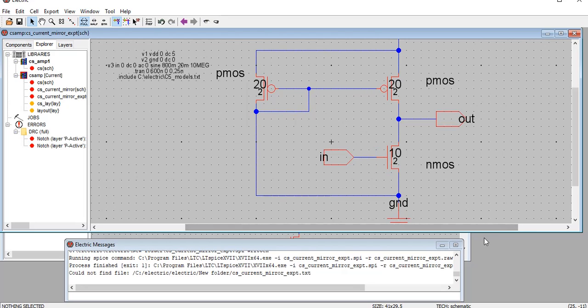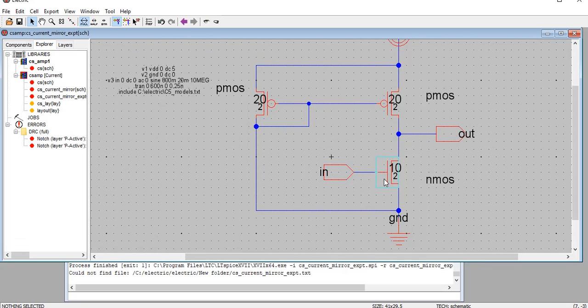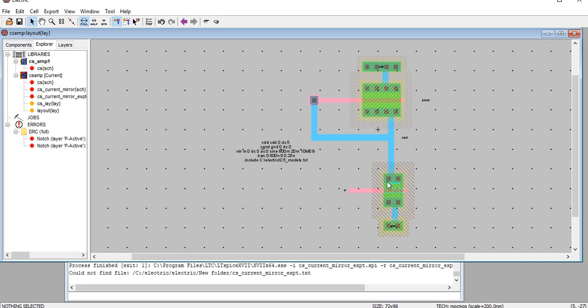So, I request everyone to perform the layout on this common source circuit, wherein it is also a non synchronous circuit, and it is also not going to follow any Euler's method or Euler's graph. So, the connection should be made the way it is going to look, and of course, this section will remain the same as what we have done in the layout section of the earlier common source amplifier. See, if I can just show you, this section is of course the same, this section is also the same. Only thing is you need to eliminate this section.